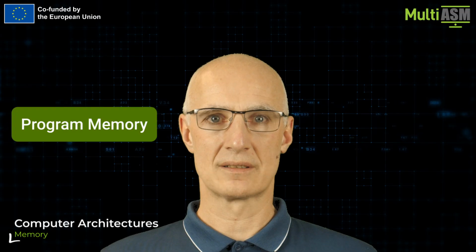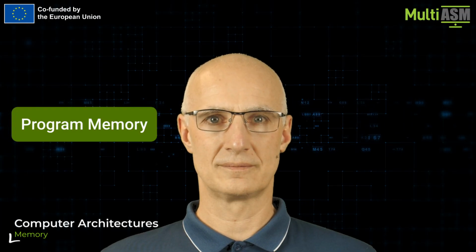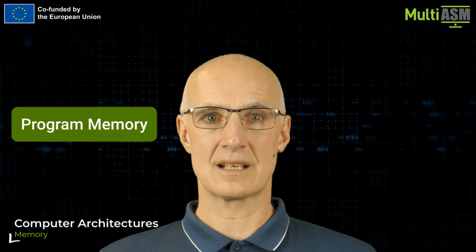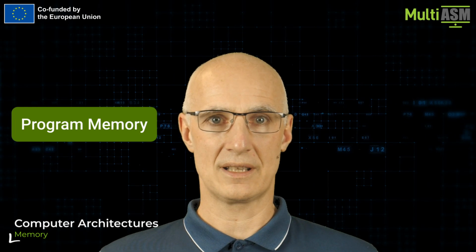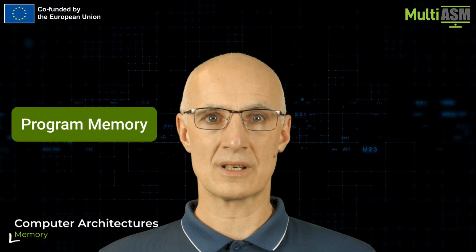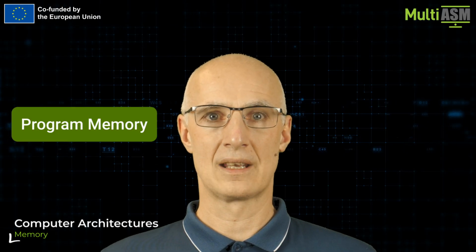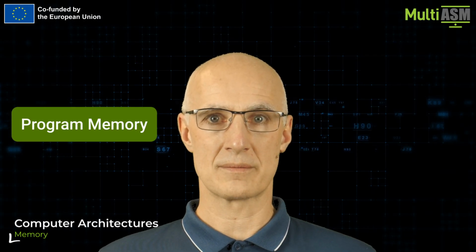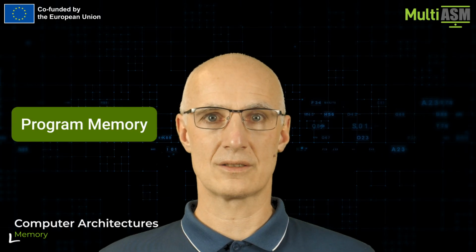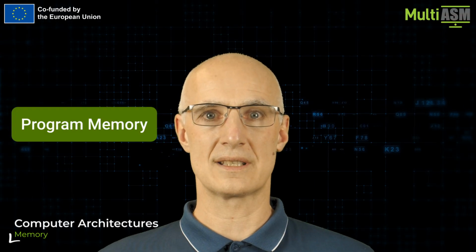The program memory is a kind of memory where the instructions of the programs are stored. We already said that in personal computers, the same physical memory is used to store the program and the data. This is not the case in most microcontrollers, where the program is stored in non-volatile memory, usually flash EEPROM. Even if the memory for programs and data is common, the code area is often protected from writing, preventing malware or other viruses from interfering with the original safe software.